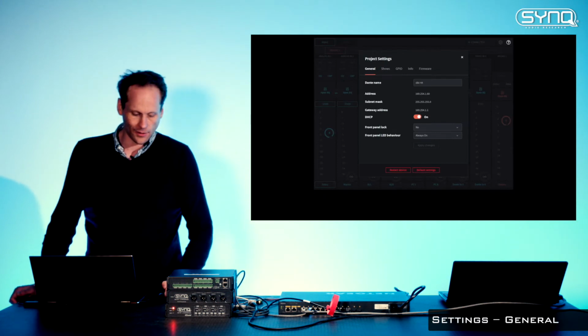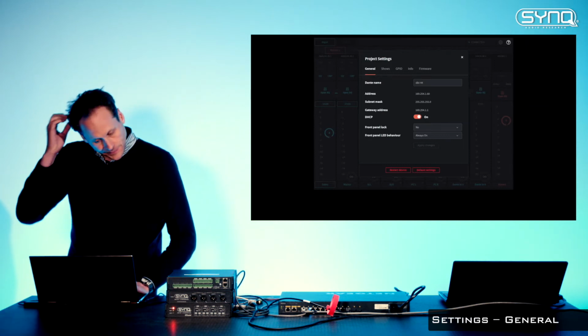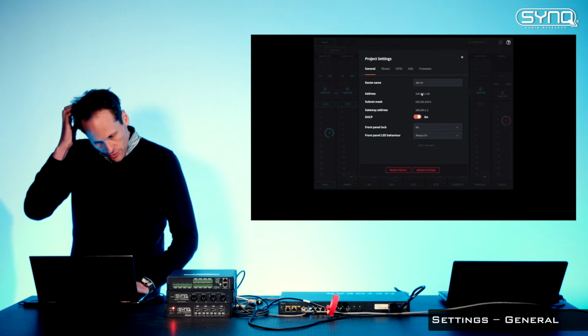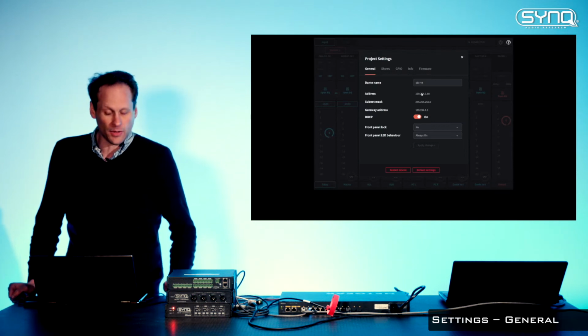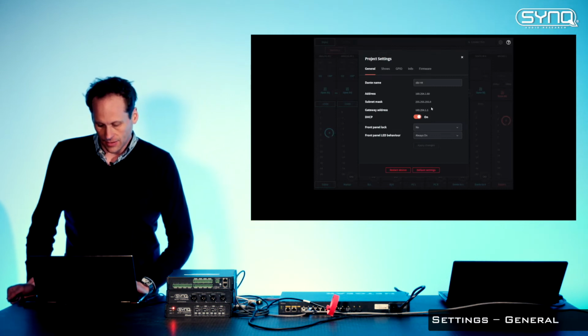As discussed previously, you can access the device by typing in your web browser web_dbi-44.local. Local is to specify it on the local network. The web interface will show you the IP address. You can also type the IP address. It's also working. Subnet mask and the gateway.